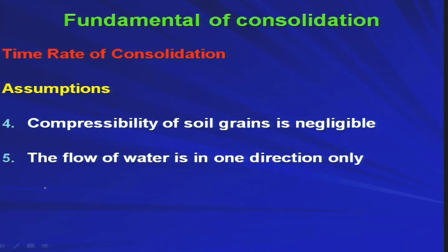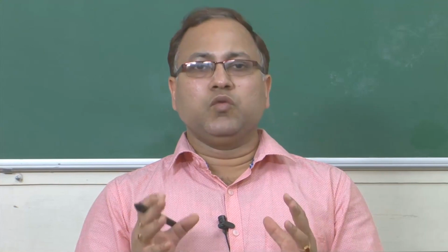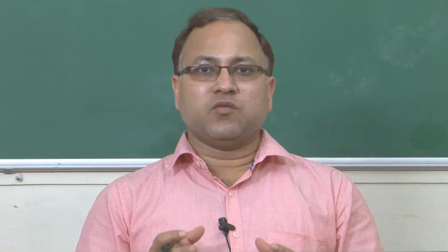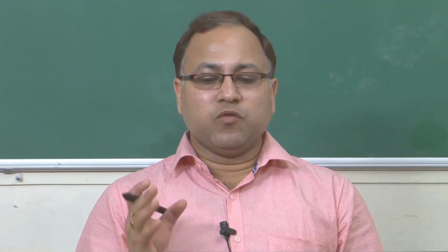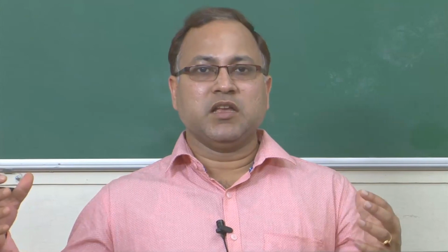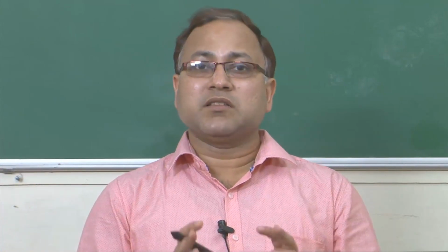Then the fifth one is that the flow of water is in one direction only. When we are trying to establish the 1D consolidation theory, the flow of water is in one direction. You can have flow in all three directions, but we are not considering that for understanding the 1D consolidation theory.